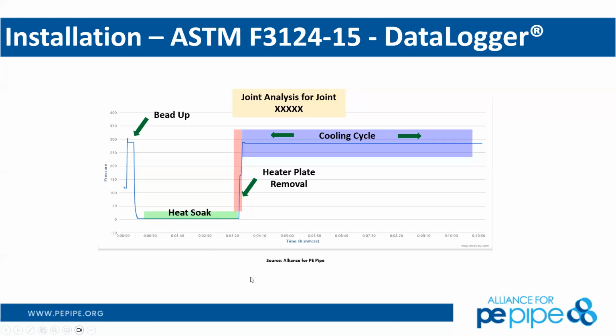Yeah, just to add to this, cooling time is really critical because of rough handling, because remember, you're going from a molten to a solid state. And the reason that interface is hourglass in shape is because the inner surface is hottest, so you get more flow for longer periods of time in that system. The heat soak under no pressure is also important, so you don't push that molten or flowable material away from those two end surfaces.